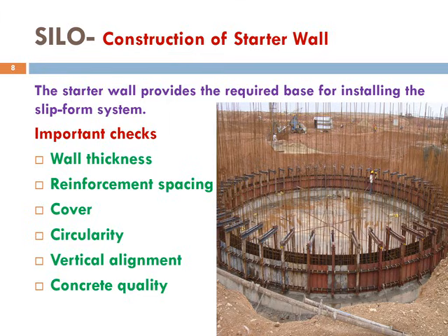Adequate concrete cover must be maintained around reinforcement. The circular shape or circularity of the wall must be checked. We must also verify the vertical alignment of the wall. Finally, the concrete quality must be checked. These checks are important because any error in the starter wall can affect the accuracy of the entire slipform construction.